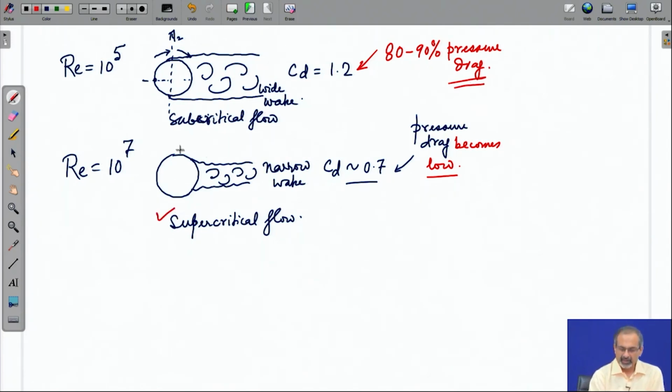flow. In recent studies, what is found is that the laminar boundary layer over the cylinder goes through a small recirculation pocket like the laminar separation bubble we were talking about, turning the flow turbulent, making it a more robust boundary layer and thereby delaying the stall. While at lower Reynolds numbers, often the laminar boundary layer separates off at a much earlier angle from the leading edge.